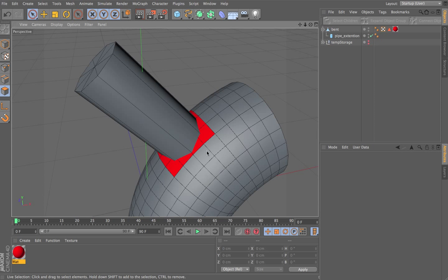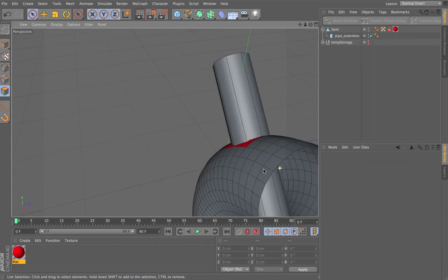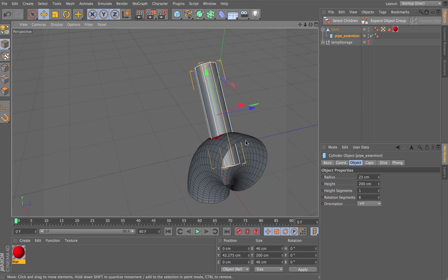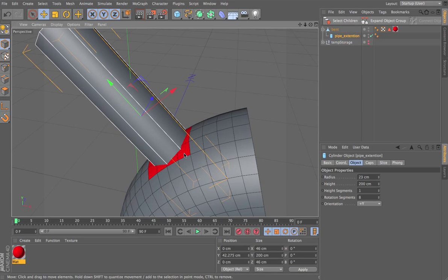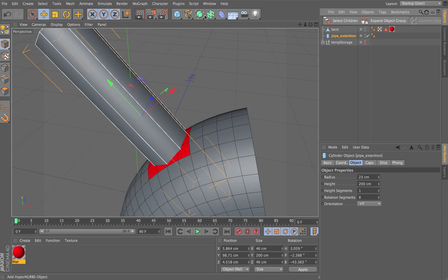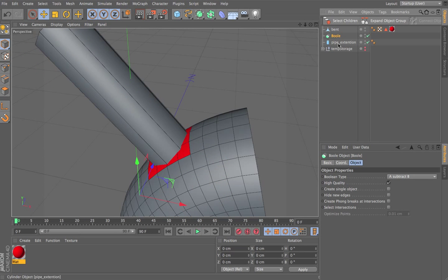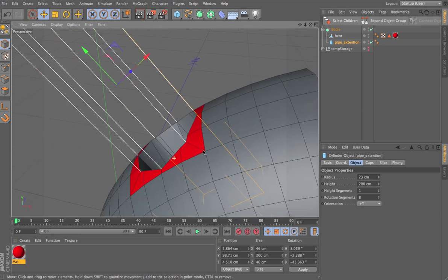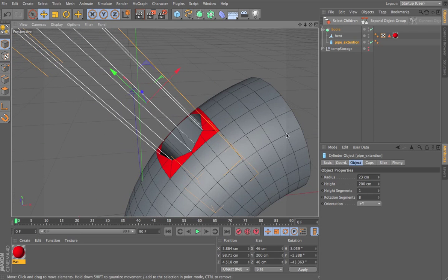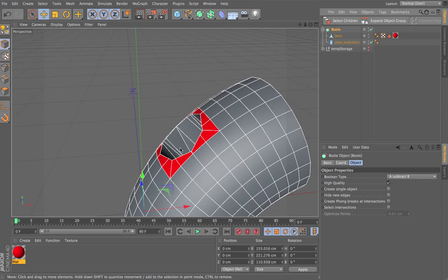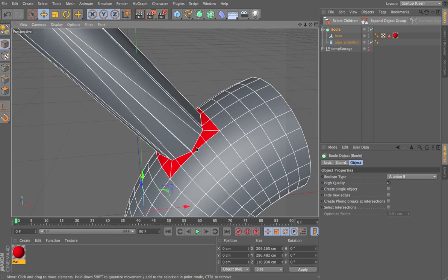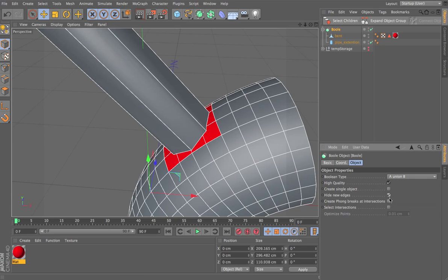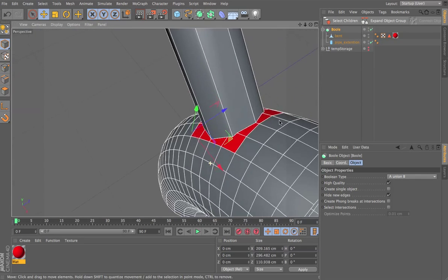Sorry again. Oh, let's continue. I've placed my cylinder. Let's see how much further down it is than I want it to be. I'm going to move it up. There you go. And now let's do the quote-unquote projection, and that will be a simple Boolean. So here's my Boolean, here's my bent object, here's my pipe extension, and basically there you go, I've got my points. Now I can choose one of my Boolean methods in order to retain the top part, and I would say union B. That's good, and I can hide new edges, and this is pretty much what I get here.